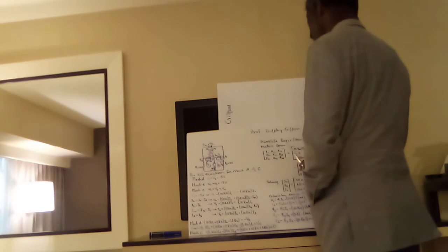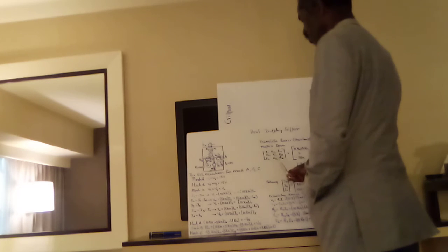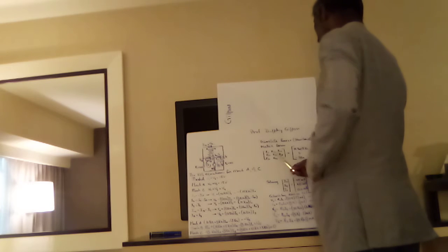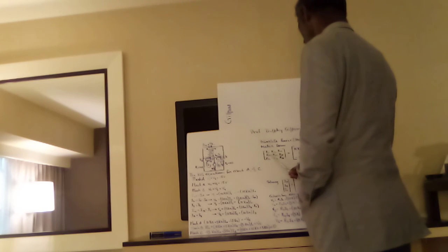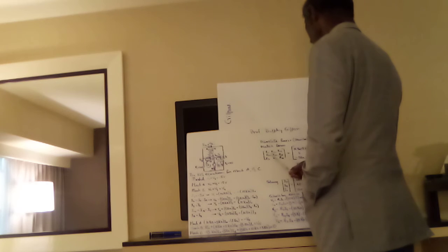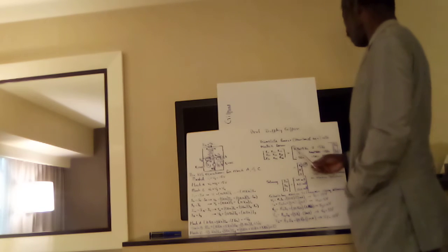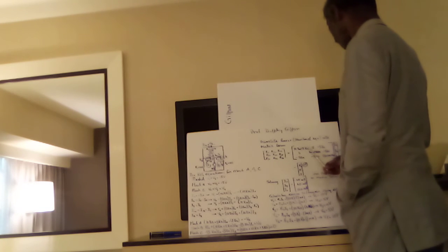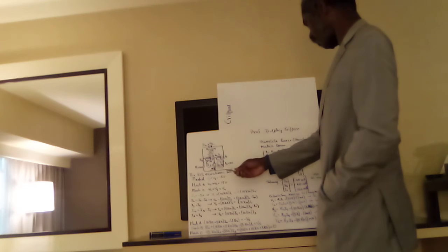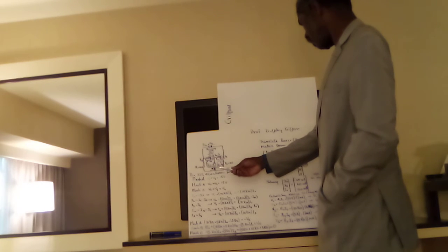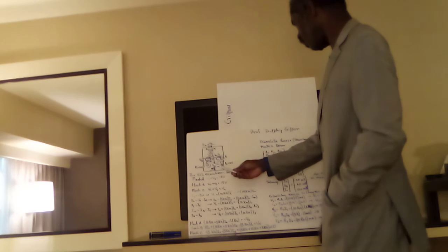And we translate the linear or standard equations into the matrix form, and we have a representation of rows and columns: R11, R12, R13, R21, R22, R23, and R31, R32, and R33. For the corresponding R11, we have 10 kilo ohms plus 5 kilo ohms, which represents this mesh 1 here.